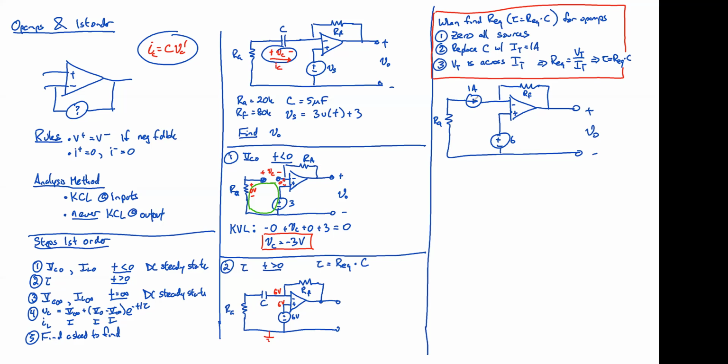For this I test, all we need to be careful about is how we define our V test. And we have to define it coming out of the more positive terminal in order to have our I test work. The fact that we drew our V test in the opposite direction of our VC doesn't matter because they're different thought experiments. Is that clear?